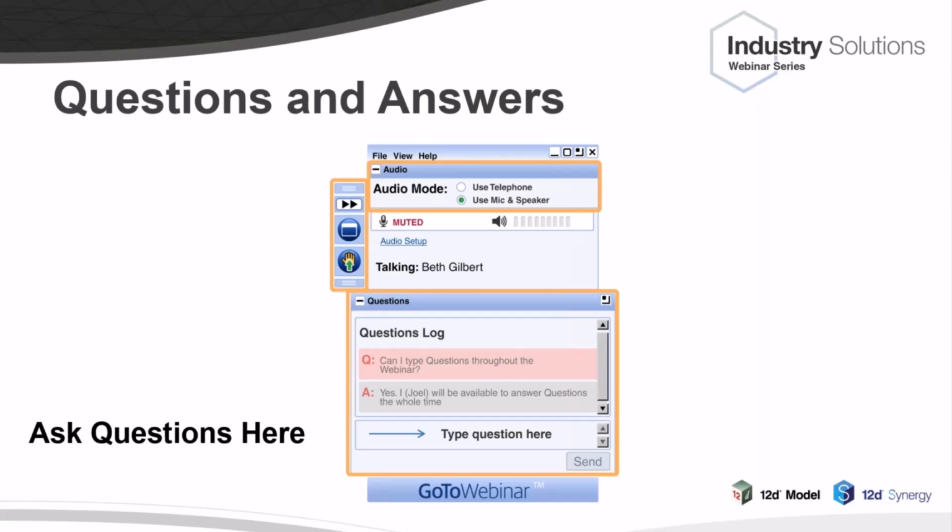Thanks, Lee. The question was, when on earth did IFC support strings? And is it only in IFC 4x3? Actually, strings have been supported in IFC, as I think I mentioned, since IFC 2, which is about 20 years ago. But unfortunately, a lot of the BIM software people decided there was an implementers agreement that said we won't show anything that's not a solid, that has no volume. But they have been there. They're under, of all strange places, IFC annotation, but there's a point, polyline, and so on.